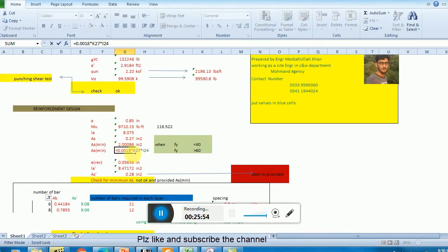Remember these are the ACI new version criteria, that if you are using 60 KSI, then your limit is 0.0018, but actually I'm using 0.0033. So that's why I changed it, because this is the ACI old version.